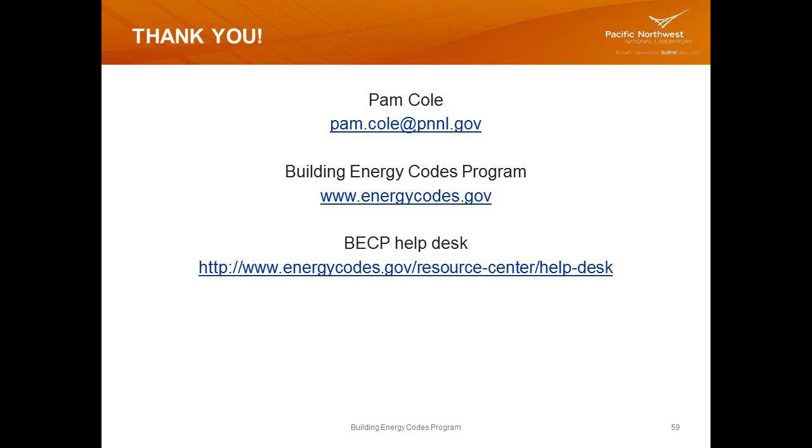Another question that came in, does your case example show the calculated U-factor values when the R-value was left out? All right, so if you choose one of the assemblies in the software from the drop-down list, it's going to calculate a U-factor automatically, because it makes some assumptions based upon the assembly chosen, whether it's steel frame or wood frame, and it's all based upon the typical components that would be involved in that assembly that you've chosen in the software.